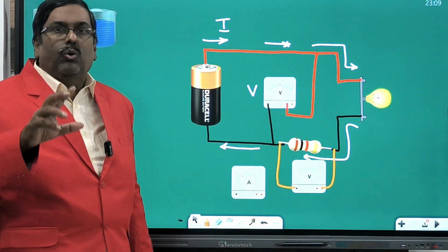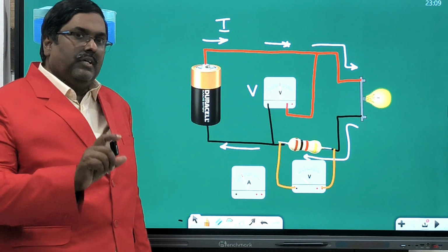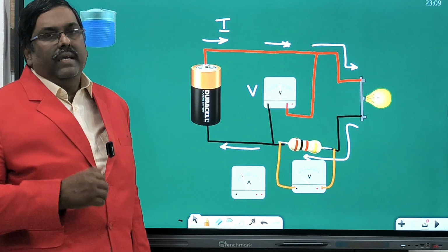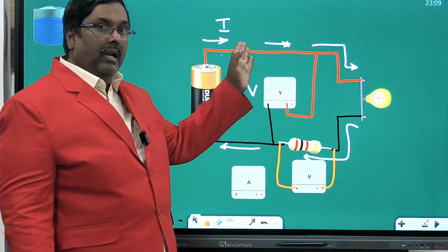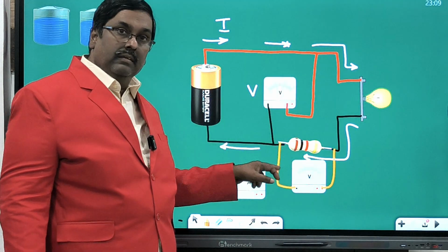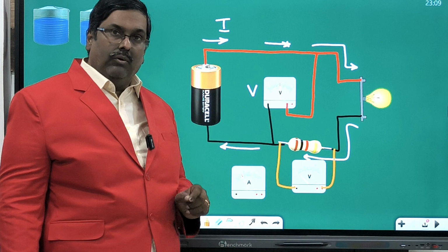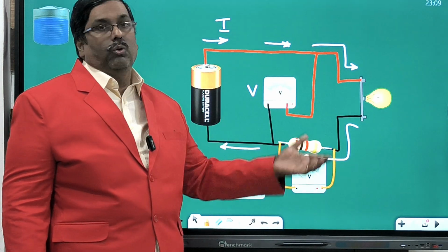So in whichever place you don't have an ammeter, but you have a voltmeter, and you want to measure the current of the motor or whatever it is, any load, then it is very simple: in series with the load, you put one very low ohms resistance, one capable of taking that much load.